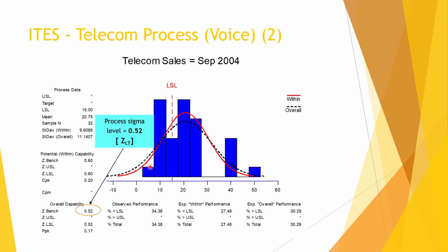We see all these numbers falling outside of the LSL. The CPK is nowhere close to where it should be. This process as it stands is not capable, not highly stable. So there's a lack of consistency.